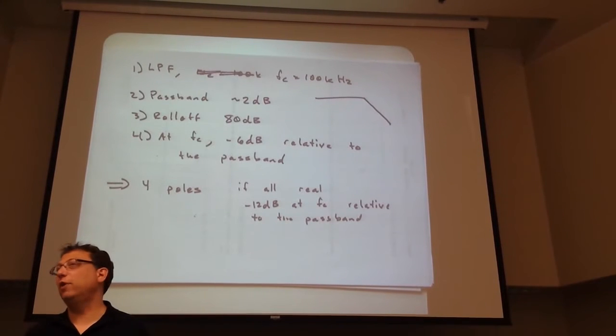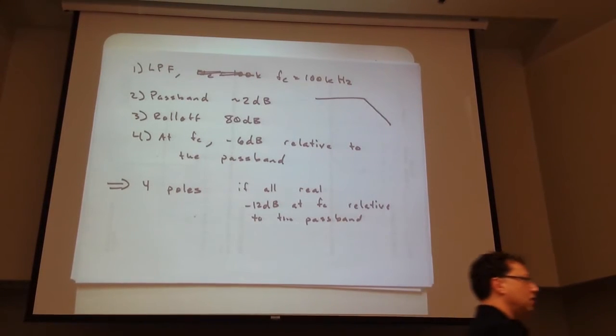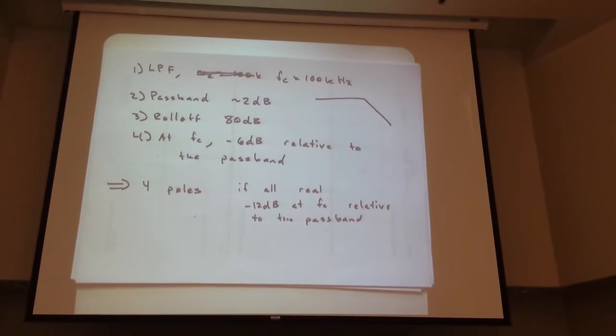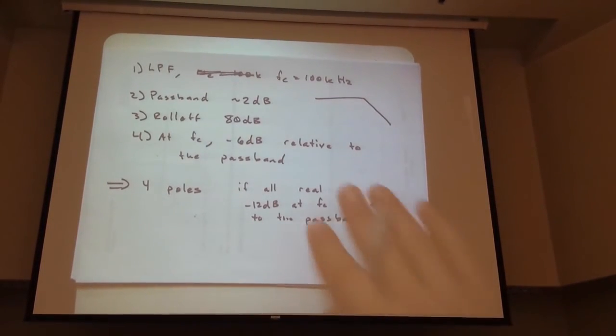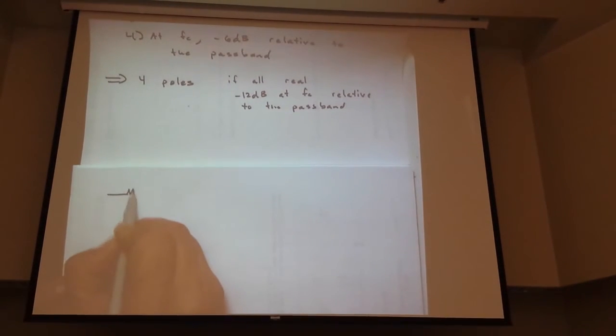Do we have to have 2 underdamped circuits? No. So we can have 1 underdamped circuit with what correction? 0 dB, relative to its own pass band, it would contribute 0 dB at the cutoff frequency, which is 2 pi times 100,000. What could the rest of the circuit be? Could be first order. So this is a low pass filter. We could do something like this.